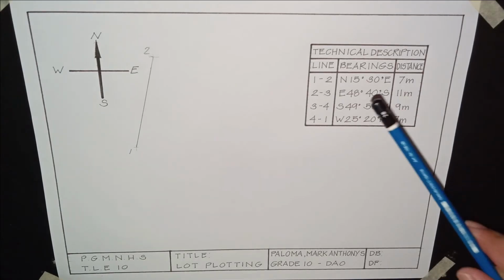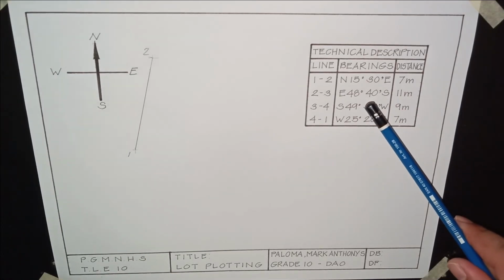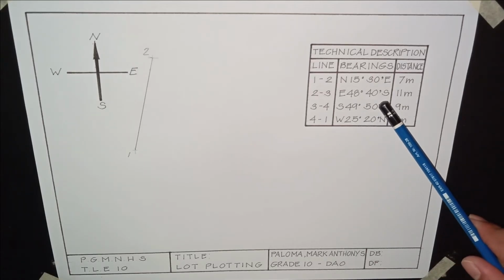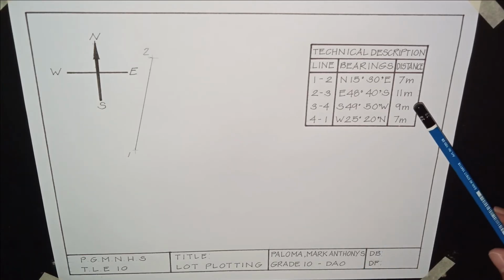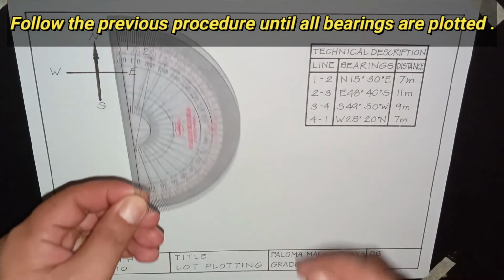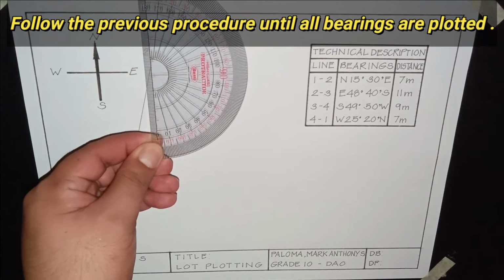Our given bearing for the second point going to the third point is east, 48 degrees, 40 minutes going to south, with a distance of 11 meters. Or, using the scale 1 is to 100, that is 11 centimeters. So how are you going to place the protractor? Since we're going to south, this is our placement of the protractor.